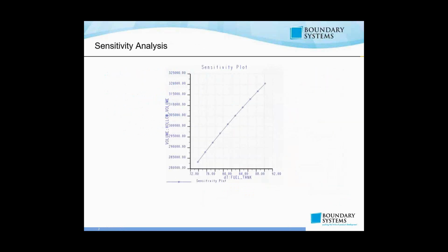And then the next step, which is optional but something you can do, and it can give you a lot of visibility into your model, is doing a sensitivity analysis. That's just a case where you give Creo a certain dimension, a certain variable that is negotiable in your system, and you have Creo change that dimension, and then plot a graph that shows how that dimension changes against your design objective or your analysis feature that you just defined prior to this.